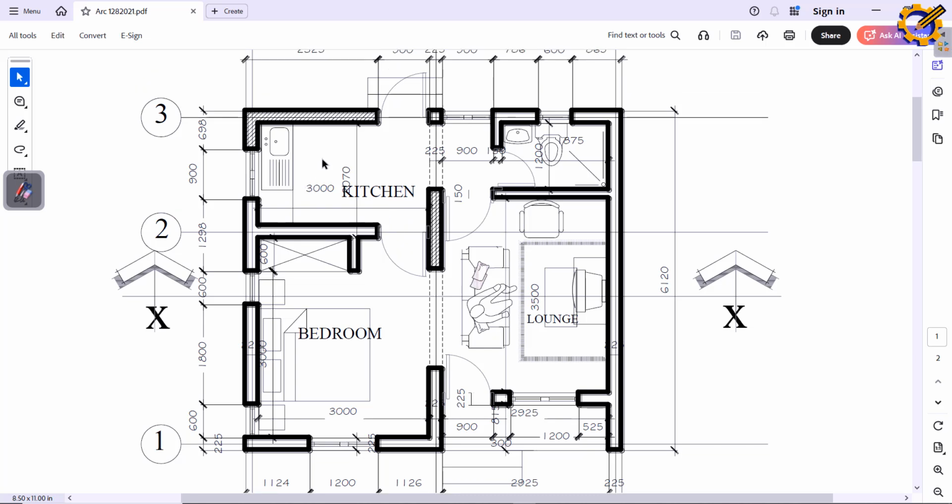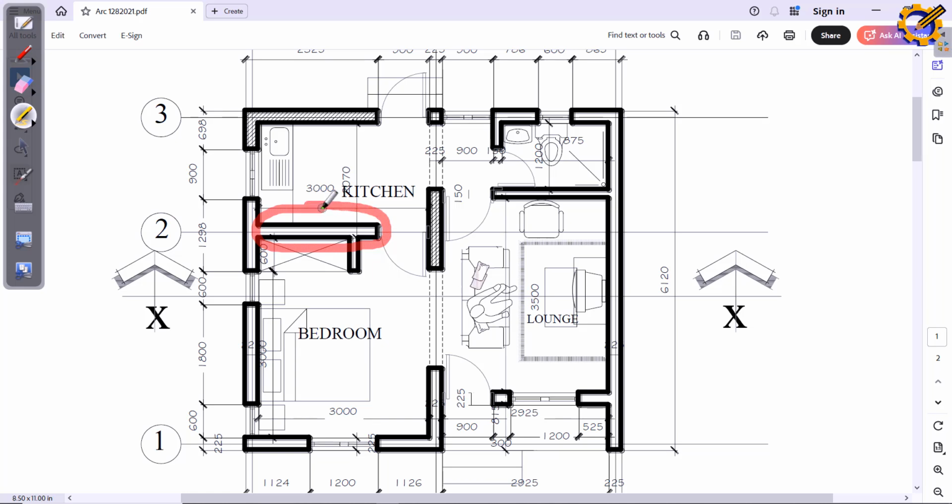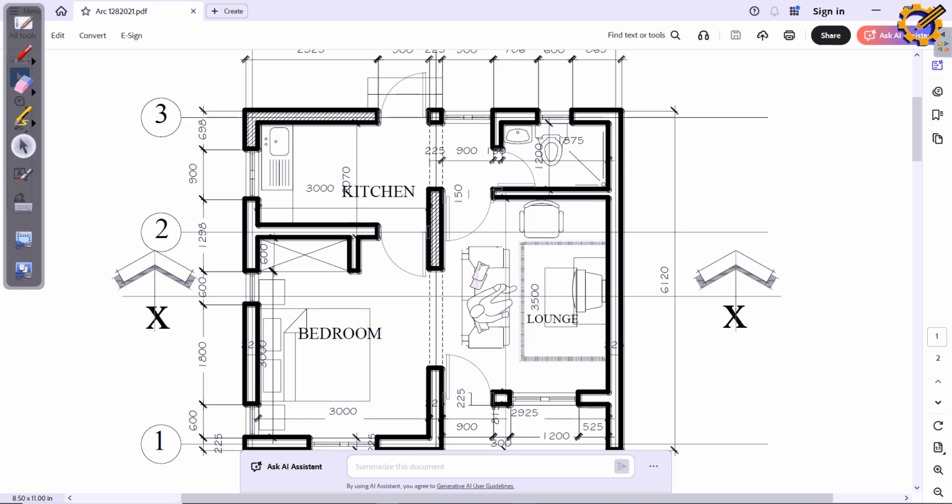But let us get this wall so that we won't mix things up. Let us actually locate this wall. To get the position of that wall, from this end of this 600 to where this wall starts, the distance there is 600, which is given here. So I'm going to offset 600 inward in my 225 in that area so as to get that particular wall.